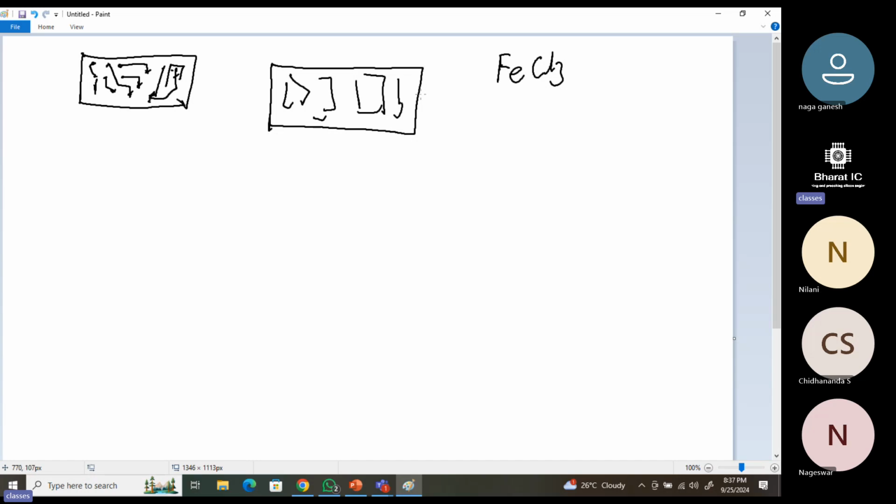Okay, FeCl3, what it will do, it will just try to remove that area of copper, and the remaining part where the ink is there, that remaining part of copper will be there. So it's a very easy step of fabrication. This can also be done with one step ahead.